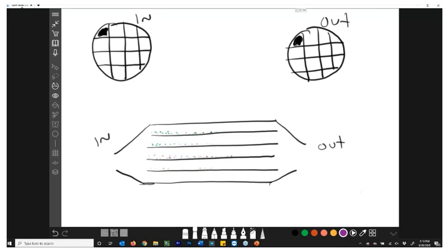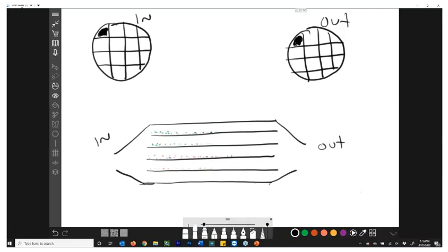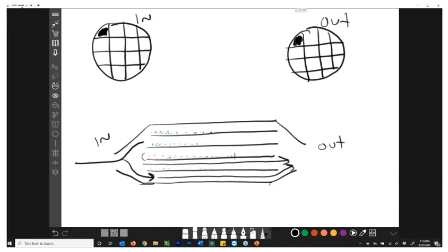So what happens is, as the exhaust gas comes in, it's going to go into a chamber, and then it's going to continue its way through that same chamber. And as it passes through this chamber, it's going to react with these precious metals that are along the walls.